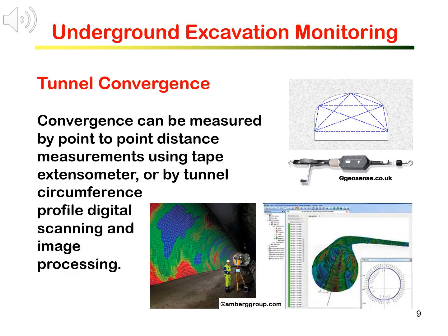Monitoring of tunnel convergence is to measure the decrease of opening size and the change in shape with time. Convergence can be measured by several pairs of points on the tunnel circumference. Geometrically, the measurements are in the form of triangles, as illustrated in the top figure. The distance between the two points is measured by using a tape extensometer, shown on the right. The method is simple, effective, and quick.